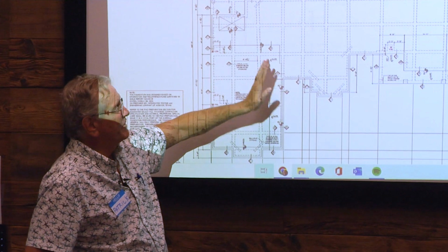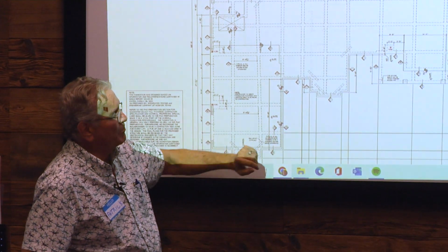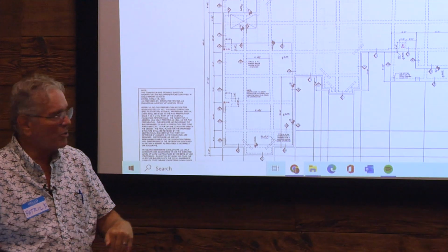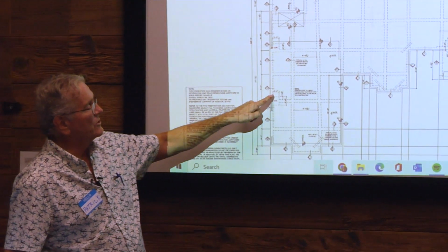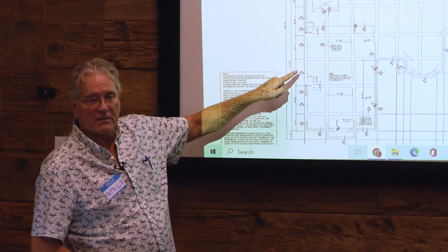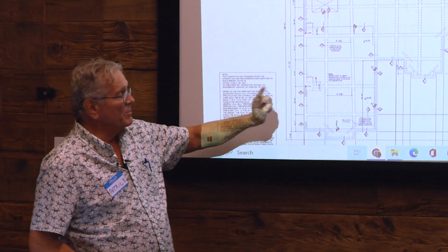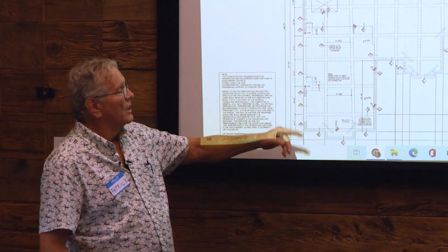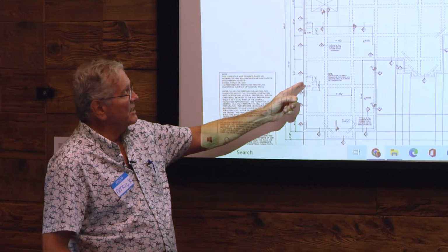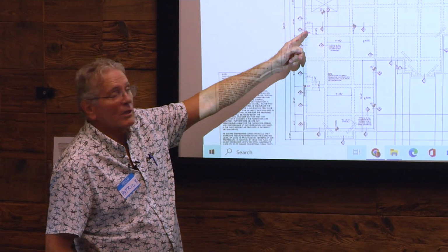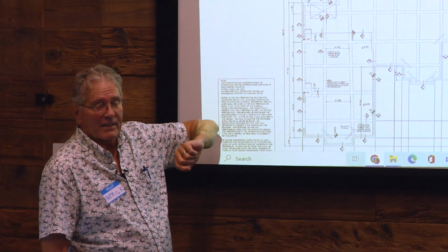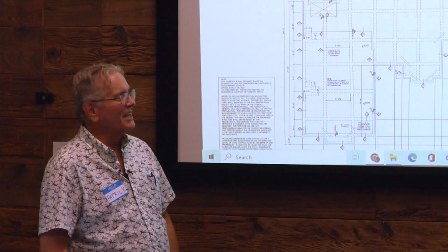Okay? If there's something that has extra bearing weight and you need to thicken the slab to take that point load, those are little pads that were dug out bigger and deeper. As a matter of fact, when the engineer came and did the pre-pour inspection, the foundation guys had not done one of these pads. Oh, they hadn't done this one up here. So he had to do that. And anyway, it was a lot of stuff.